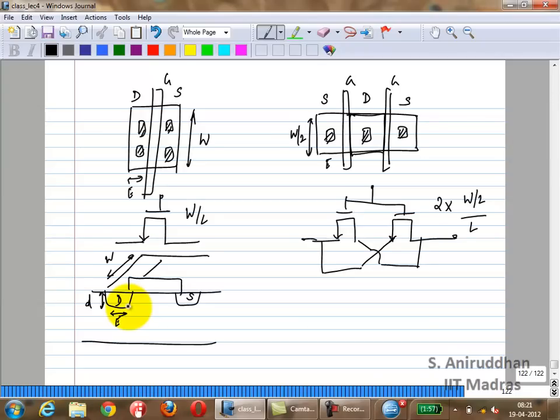First of all, what components can you see for the drain bulk capacitance? You have some drain bulk capacitance like this, definitely, on the bottom side. What does that depend on? It depends on the area of the bottom, which is E into W. Correct?